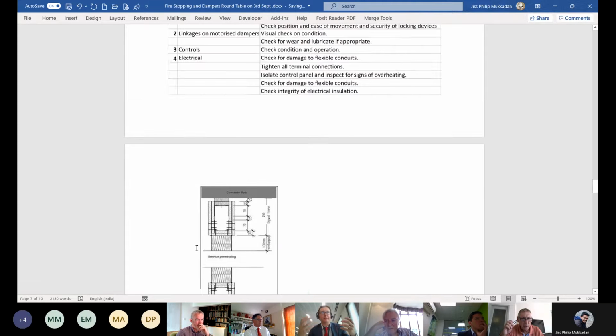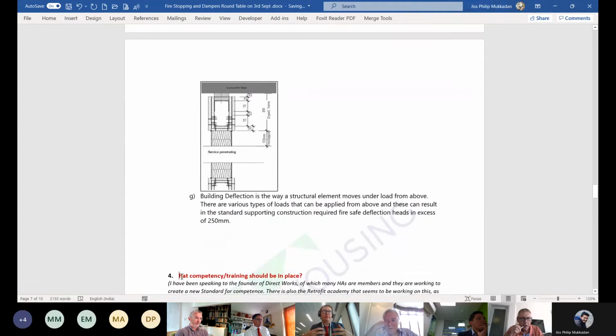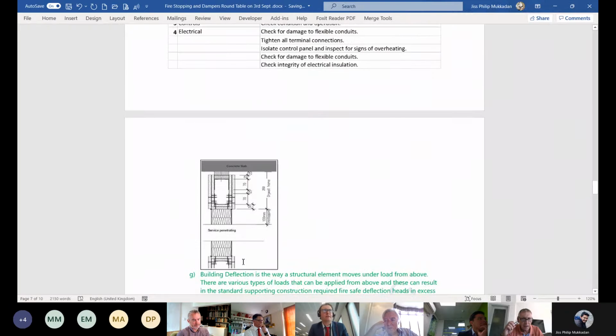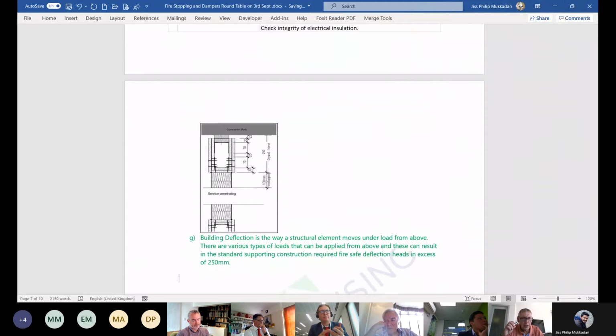So when you look at it in context, if a big construction company like Mace goes away and procures the MEP contractor to buy all the kit and do all the builder's work holes, they're doing it in isolation of understanding what deflection is, how a wall's built correctly, and what thickness of walls are required for the detail. And when the drywall contractors are appointed later on, it all comes out of the woodwork. This is why you get absolute poor quality on sites with some of these installation details, because of the way things were being procured. You understand what I mean?